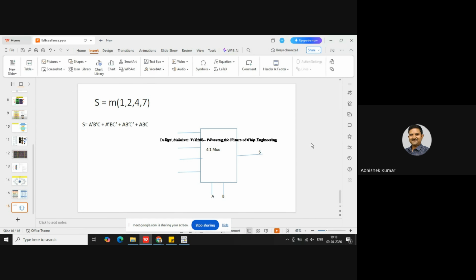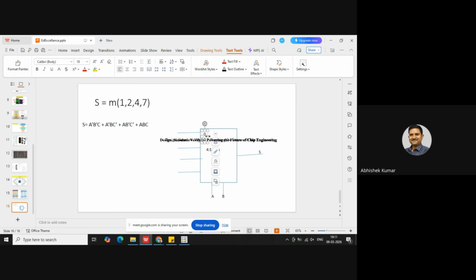Okay, here we are to make the multiplexer input S. Now, what can be the input here that is going to represent C? In the C, we are going to write the equation simply by means of comparing. We know that when AB, this position represents 0, 0. Afterwards, the next position represents 0, 1, then 1, 0, and 1, 1. That is the option for a 4 into 1 multiplexer.